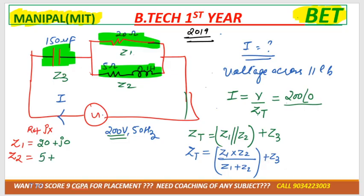R is 5 ohm plus JXL. XL, as I told you the formula, is 2 pi FL. Here L is given, not XL. Many students make a mistake here. How will you get to know?